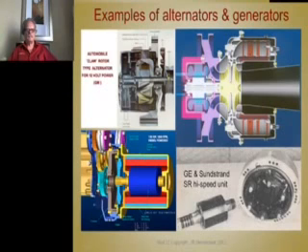Because of this fault tolerance problem, GE and Sundstrand developed switched reluctance generators for jet engines. They had the compressor blade down here and the combustion blade here, and this generator was mounted right in between the two, instead of cantilevered off the end like this shows.